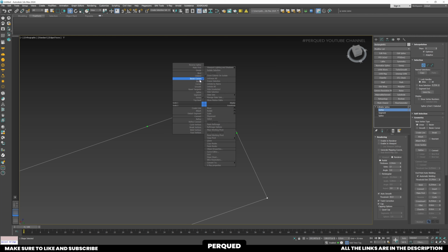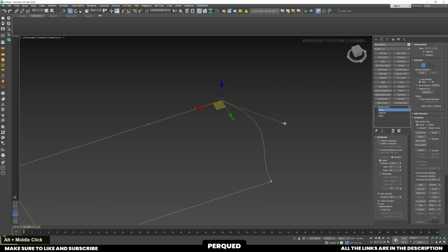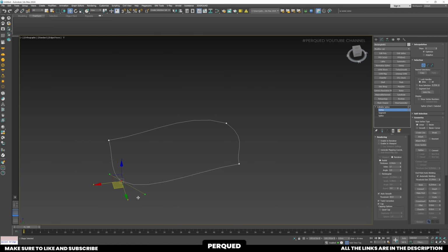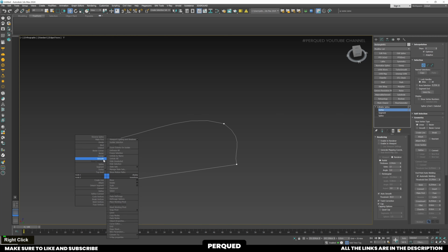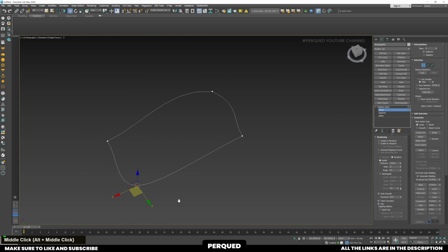Let's select one vertex and select Bezier corner. Now what that will do is that it'll give you the ability to adjust the spline from both ends of the vertex. If you can see, there are 2 green color helpers that appeared, which can help you move between vertices like this. If you set it to only Bezier, then it'll give you the option to move the spline like it's connected from both ends. Now if you make it corner, then it'll simply make it cornered, and the same with smooth, it'll make the spline smooth without any control. I hope these 4 options are clear to you.